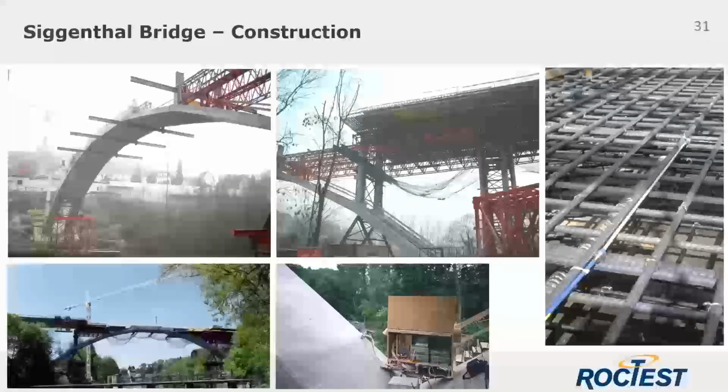So this is the construction of the vertical columns first, and then the deck over the arch. And here we can see also the towers, the 2 towers that were used to temporarily stabilize the bridge in order to allow the construction of the columns and of the deck.